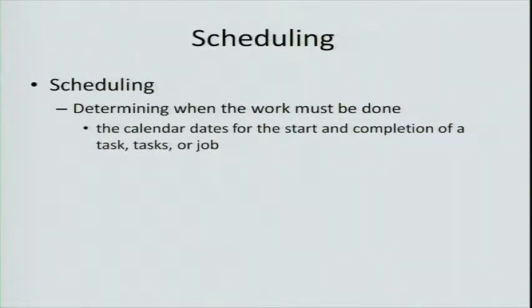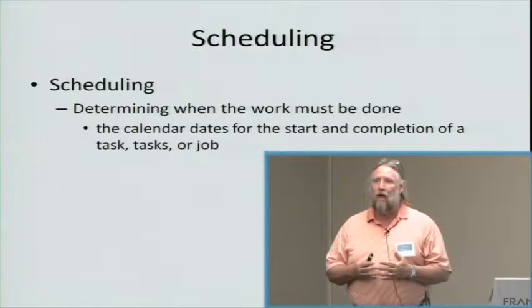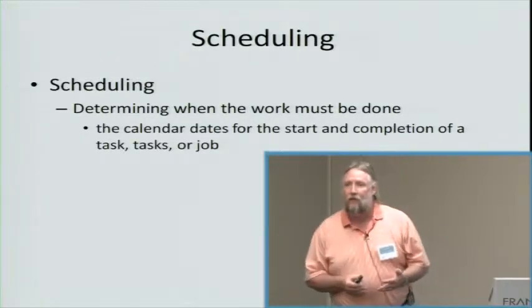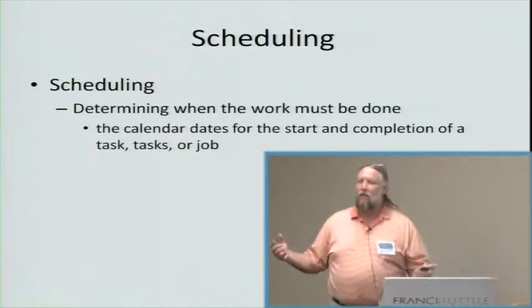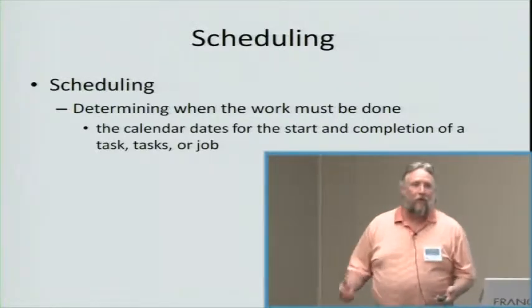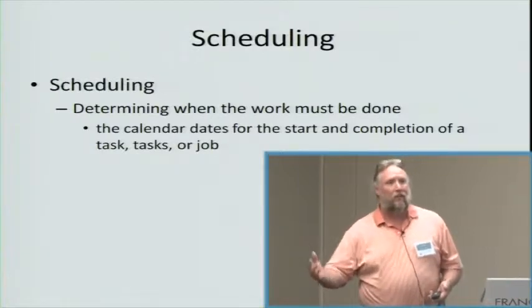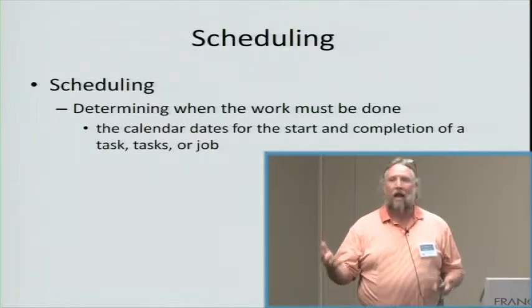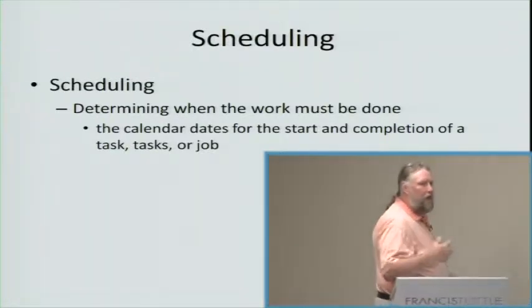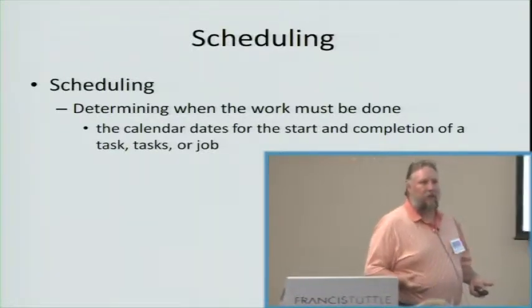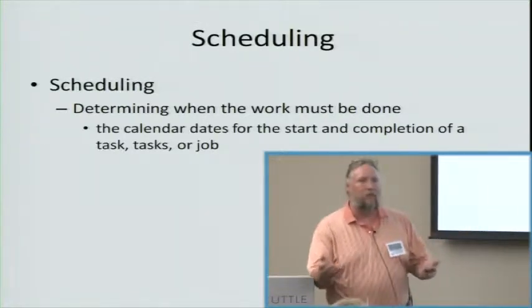Scheduling basically puts all the items that we put into the plan into a sequence order in which we now have taken time into consideration. The plan just tells us what we're going to do. If I'm putting in foundations, I'm going to dig foundations, I'm going to set the steel, I'm going to pour the concrete. I have a plan. But the schedule tells us how long it is going to take us to dig the foundation. We now put an estimate to that time.